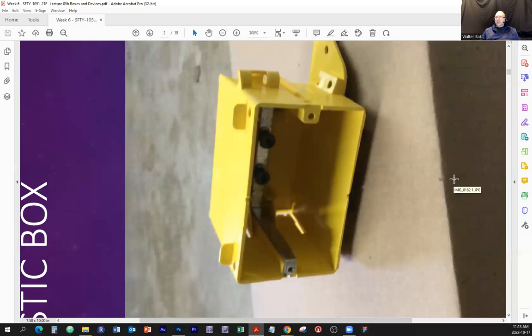If that piece of conductor is terminated on a screw terminal of some sort of device, and from that it also continues, on the same potential, to the next box and its grounding terminal, then that next box is also grounded, but it is not grounded with a straight conductor that goes to a true ground.